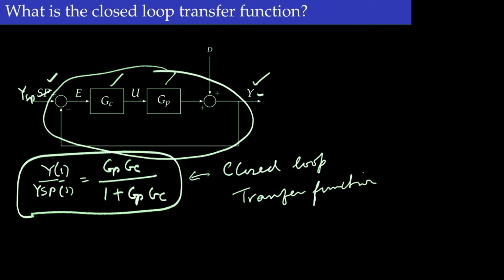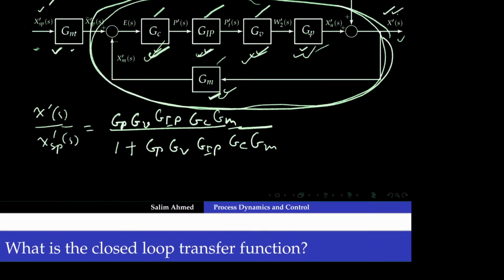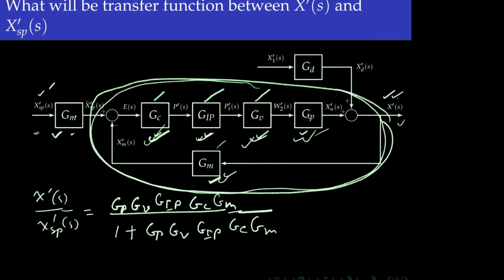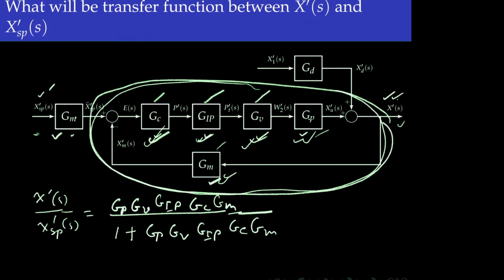Now, this simplified form of the transfer function is used to design the controller, meaning that when we have a process with all the elements, we find a simplified model to design the controller, because most controller tuning algorithms are based on either first order or second order process. However, when we try to implement the controller, we need to consider all the elements, because these are the really existing elements and the control performance depends on all of these different elements.